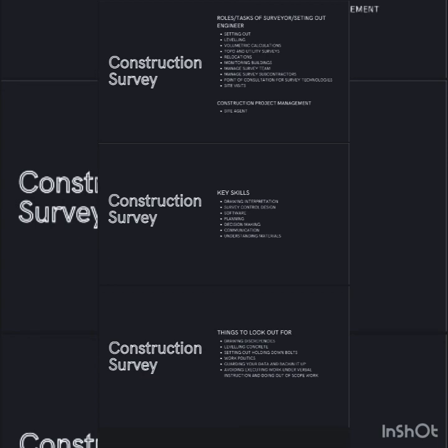If the machine is out of spec, let's say you're given a 20-second total station when you're working on a building, that's not proper. You need maybe a 2-second machine. So if there's a problem with the machines that might affect the accuracy of the project, please flag it. Everything that's wrong, flag it.